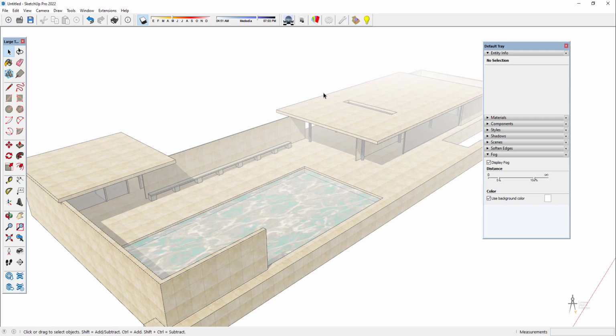Lines that have to do with architecture. Second step would be to export them or import them into SketchUp. Once you did that, we created our faces, intersecting, remember creating the rectangle and intersecting it with the other rectangles. And after we did that, we rotated our sections so that we could use the height as a reference.